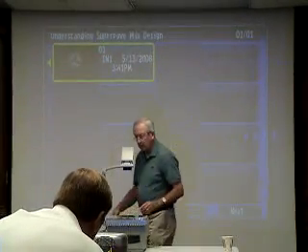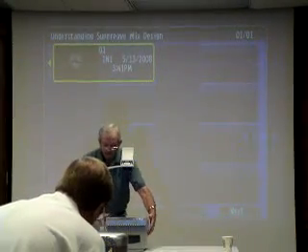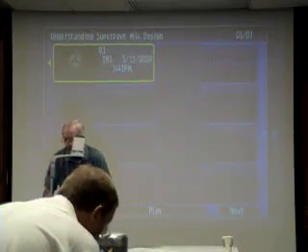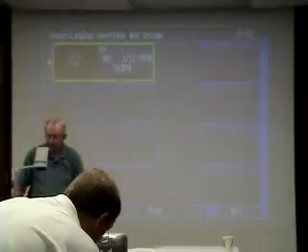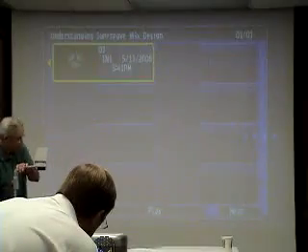One thing I would ask you to do is when they start talking about the compactor that you use to compact the specimens, the mixes, the SuperPave gyratory compactor. That's one of the major differences in the SuperPave design process and the old Marshall procedure that we used to use.